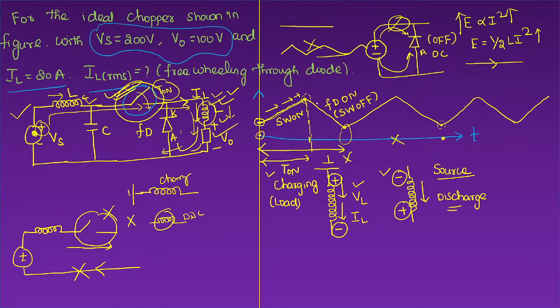Okay, sir. Now I hope you all have understood how it is working here. Come to the conclusion. The question is the output current that is freewheeling through the diode. Now you know freewheeling action will take place only when the switch, the thyristor, is in the off state. So this is the off state period of the thyristor, the blocking period. During this period only, we are observing the output current traveling through the freewheeling diode.